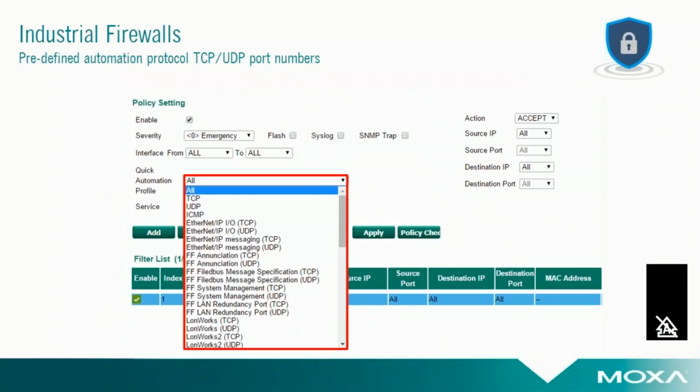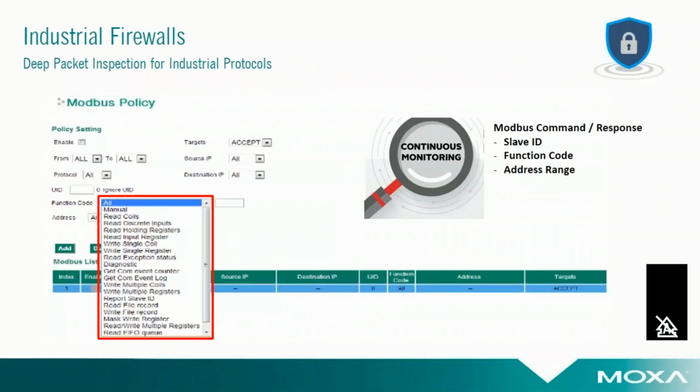So let's look at a couple of things about industrial firewalls. One of the questions I get pretty frequently is what's the difference between an enterprise firewall and an industrial firewall? So aside from the physical differences, as far as one being designed to operate in a nice air-conditioned server room versus another that's designed to operate out in the harsh environments of the factory floor, the types of traffic that they're filtering are often very different. And the skill level of the people using these devices also varies, whereas IT people typically have somebody that understands the complexities of developing fairly complex firewall rules. On the OT side, people understand the control traffic that they're used to using, but they may not know the specific TCP or UDP ports associated with those.